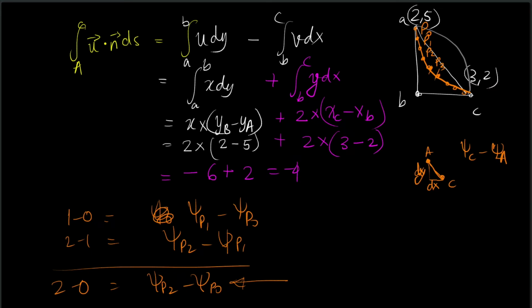You can also try to draw the line AC and try to justify the entire calculation, that is doing u dot n cap across the line segment AC. It involves finding out the equation of the line, finding out the slope of the line AC, the orthogonal to that direction, and then finding the effective flux. It's quite simple. Have a go at it.